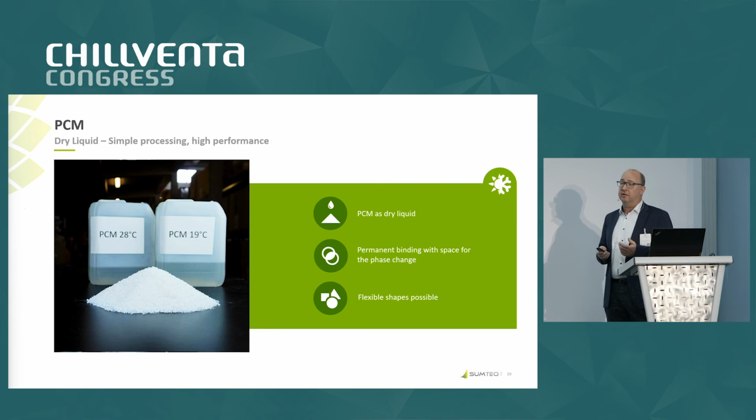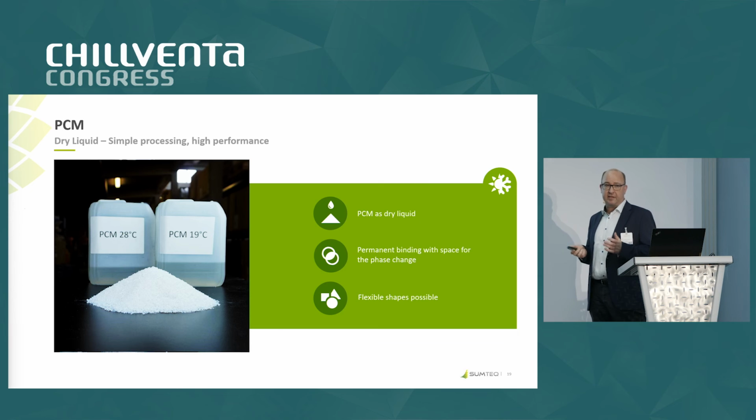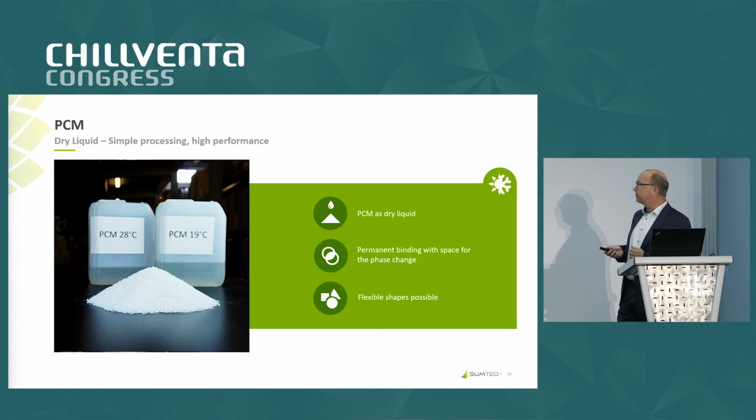It's especially interesting for tubes, pipings, and so on, or for vessels to keep the temperature inside at the needed temperature. For example, you want to keep 40, 60 degrees inside. You use a PCM of 40, 60 degrees and make a cover of another insulation around, so you have a very long performance.